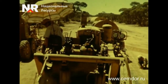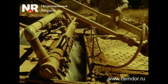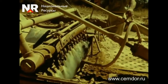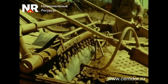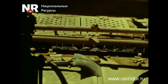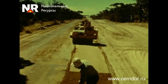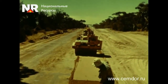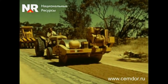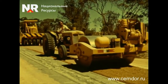The required amount of water is supplied from a tanker moving ahead of the mixing unit. If necessary, a stabilizing additive is introduced, which can affect the water balance of the soil cement system. To achieve maximum density and therefore maximum strength, the soil cement must be compacted as soon as possible, right after mixing. The roller should follow immediately behind the mixing machine. Vibratory rollers have proven extremely effective for the initial compaction of certain types of soil.